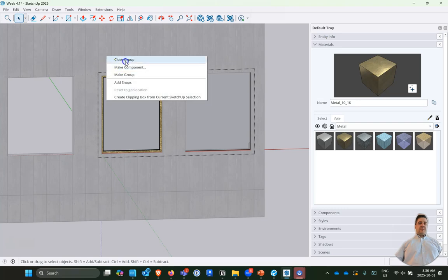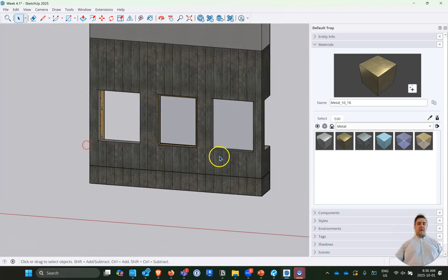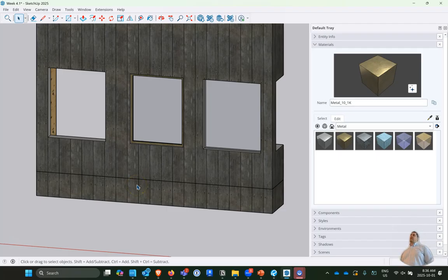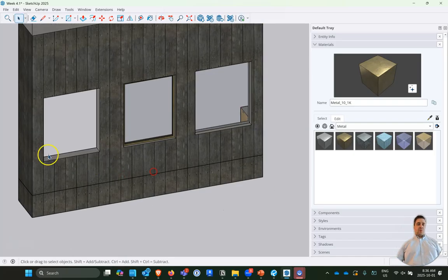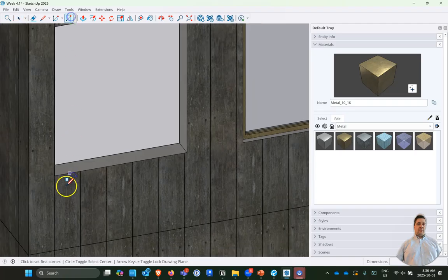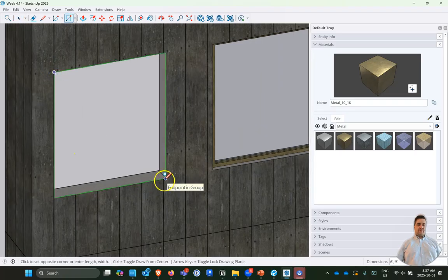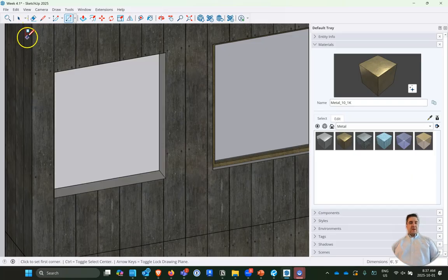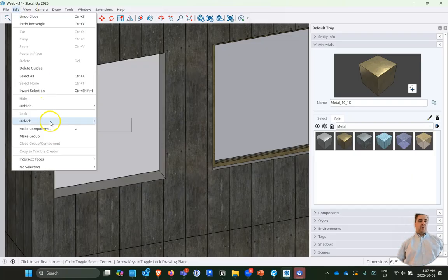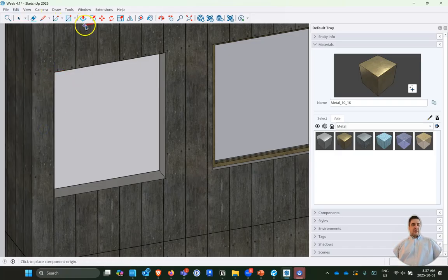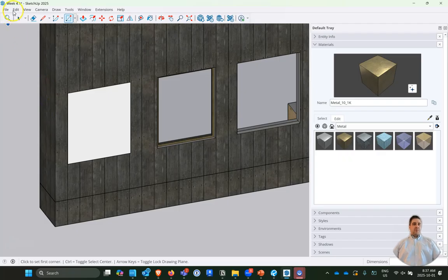There is another thing that we can do. Maybe we like that one window and we want to apply that to another place. And as you notice, I made all the windows the same size, so it's really easy, obviously. And so what we can do here, let's go to this window here and trace it. And actually, before I trace that, let's go to make another group. But this time, instead of a group, we're going to make a component. And let's go to our box here and make this right inside my component or not.